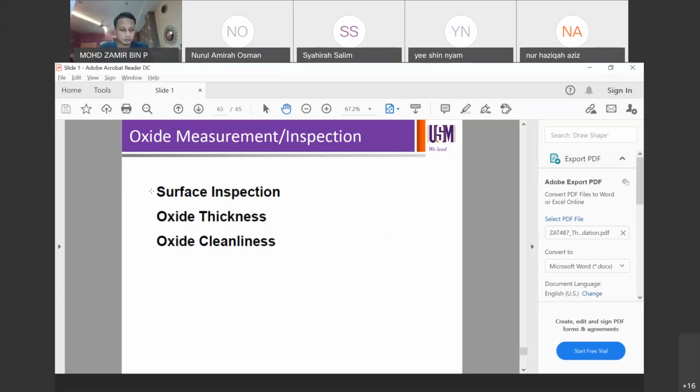If you talk to any diffusion or oxide engineers, the particle problem is one of the biggest challenges in the fab. Where does the particle problem come from? It can be from your quartz boat, your gas line, your wafers, or whatever ambient is running the process.